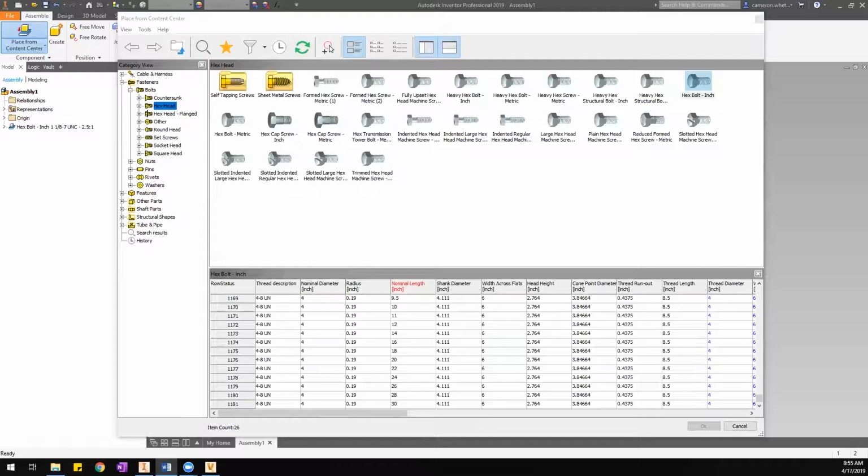If you have a multi-user environment, with more than one designer, and you're going to use a standalone setup, one thing to consider is that all of these common files are going to get duplicated. If user Dave places a 5/8 bolt into one of his assemblies, and then user Michelle places that same 5/8 bolt in her assembly, because they're in a standalone environment, they're duplicating those files. They're both using the same one, but they've both got a copy of it. So all your files are going to be duplicated, and that's just something to think about with a standalone environment.